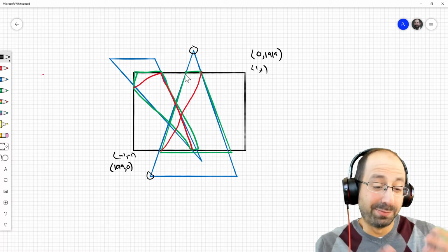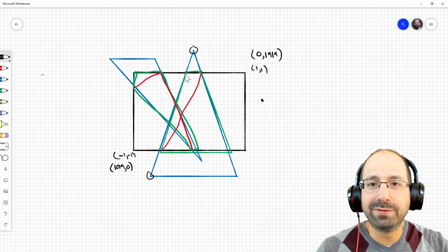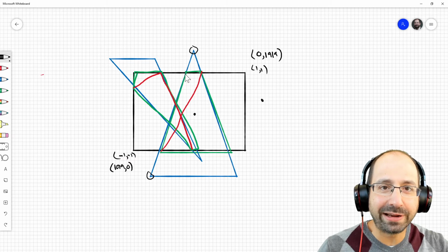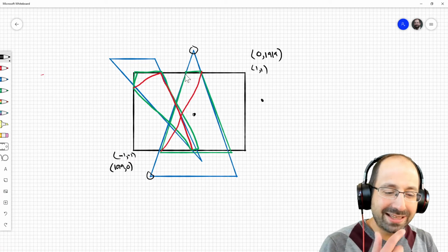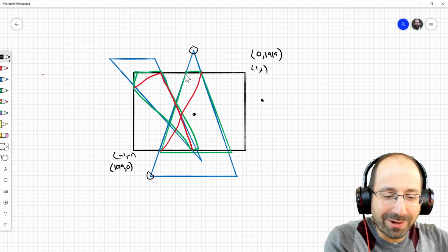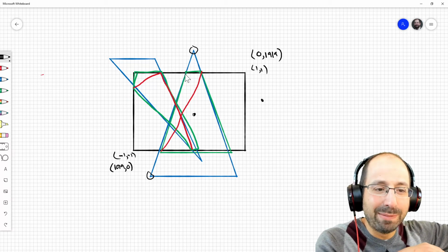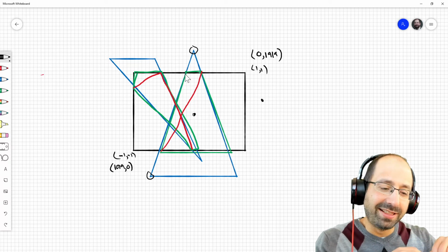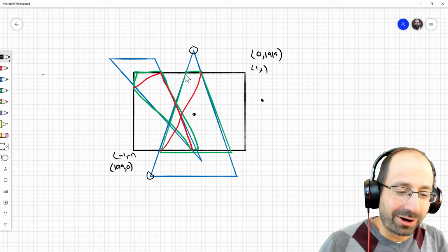Think of it as a buffer overflow if you want to, or if I'm trying to draw a point that's out here, even though it's supposed to have been clipped, that's actually going to correspond to something that's going to be on the screen right around here, right? Or some point in the future rows, right? And some of you, as you were testing MP1, may have been seeing that kind of effect, right? Where you were off by one and you were seeing it at the top of the following frame. If we didn't clip, if we instead took the approach of draw and let the memory hardware kind of sort it out for us, you would have all sorts of really weird artifacts.